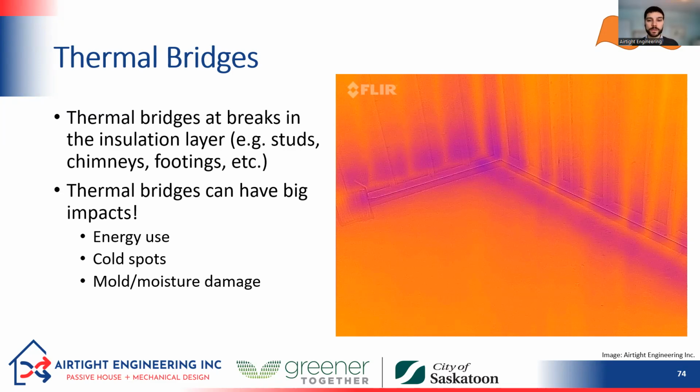In this picture, the thermal bridge that we're seeing, you can see the sort of purple aura happening here. This is in a basement. That is the footing. So there's probably insulation on the outside of the foundation wall down to the concrete footing, but not underneath the concrete footing. And same thing on the basement floor. There's insulation up to the footing, but not underneath that footing. And here we can see very clearly that there's extra heat loss happening through that footing.